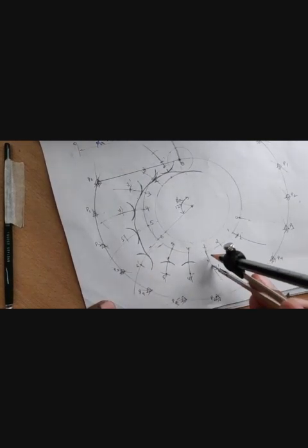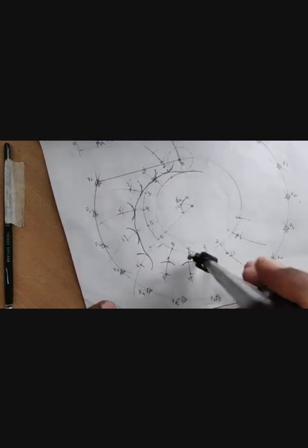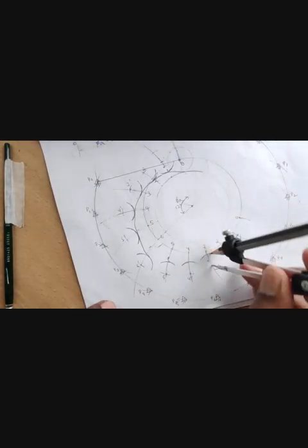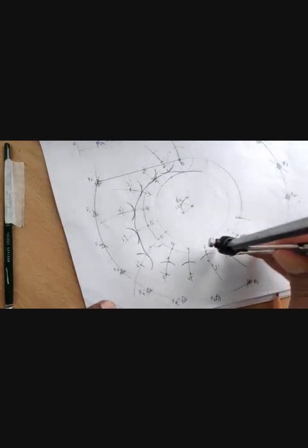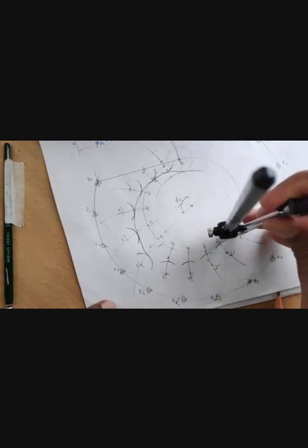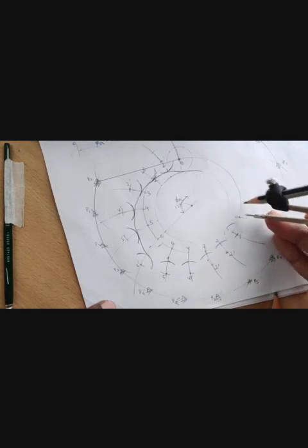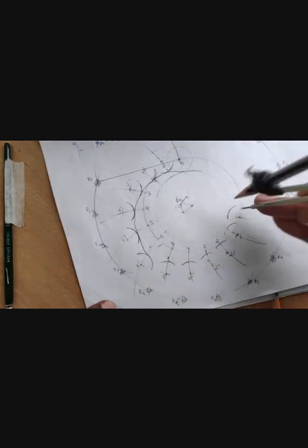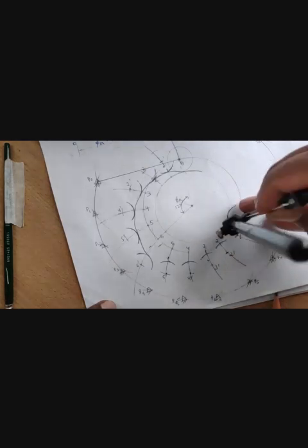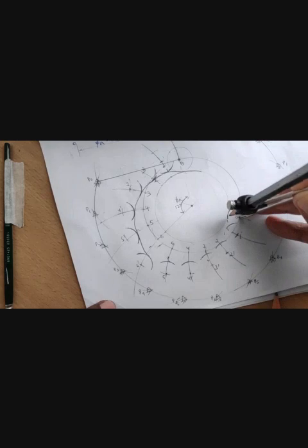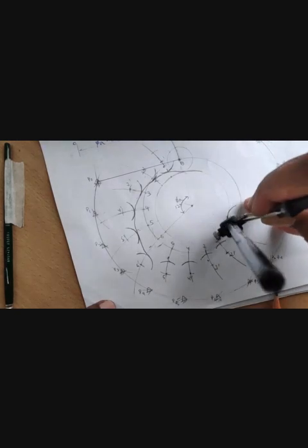So here, keeping the constant radius of 10, which is the roller circle radius, you draw arcs through each of these points, and of course at 0 the roller will be here, because there's no lift. So it's not easy to draw small rollers. Very difficult.